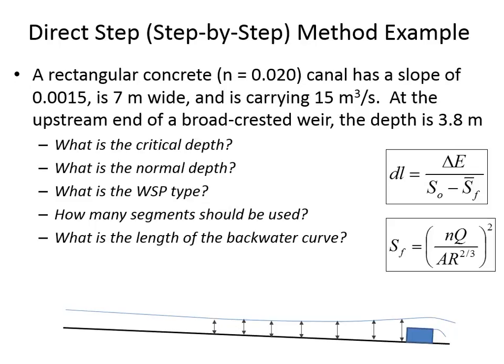And even on a smaller level, when someone puts in a culvert, like on a small creek, they're not supposed to put in culverts that will choke the flow at all. It's supposed to be able to pass the 100-year storm through a culvert without any backwater forming. And so, when there are obstructions in the way, you have to have some sort of an analytical method that will tell you how far upstream the water is going to be disturbed by an obstruction. There could be homes that if the water level rises too much, it's going to wreak havoc with the home.